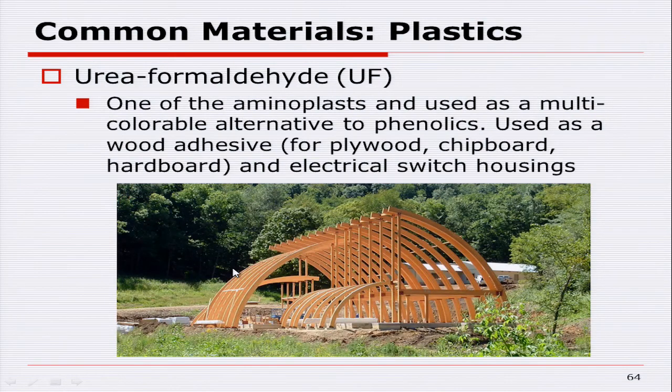Urea formaldehyde, again, another one of the phenolics, just like melamine formaldehyde. And this urea formaldehyde is really the adhesive that we typically use for exterior applications of lumber. Now, also interior applications. Basically, all those engineered lumber products have this as an adhesive. So they can be used outside, inside.